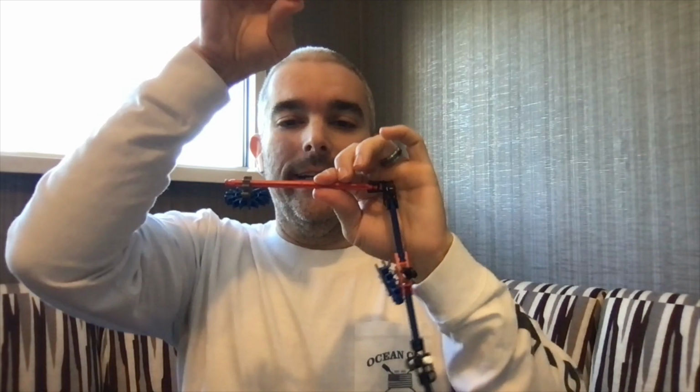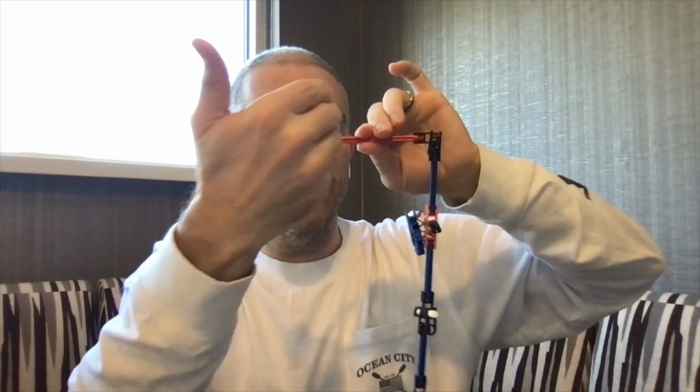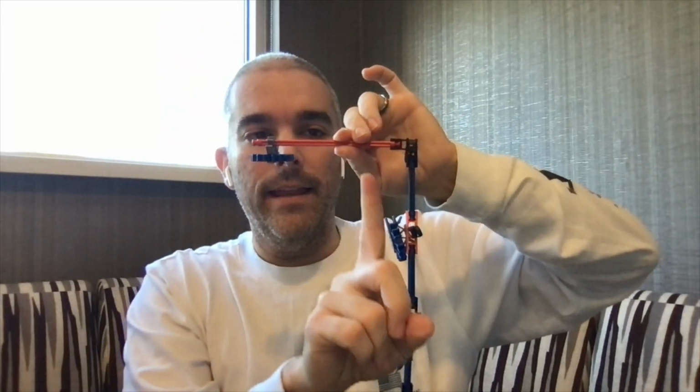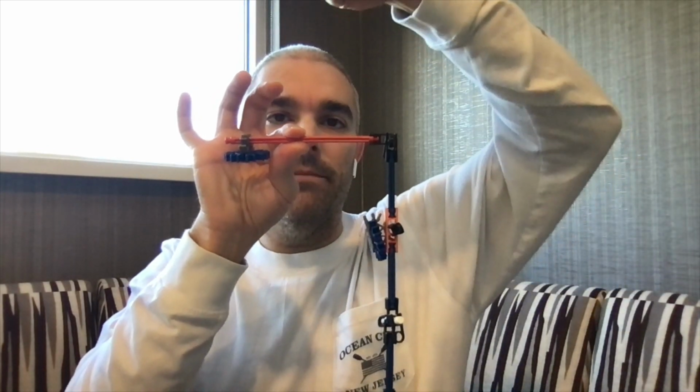All right, one more time here. We're going to look at the shear at point F. So you have to imagine, like, if I clipped this or I broke it, and so again, I'm going to apply that positive direction. Again, because this is a fixed end, I really can't move it on that side. And so it's on the right-hand side that it's going to shift. Now, again, positive shear is going to be down on this side and then up on this side. So since this can't move, this is just going to shift up. So it's going to shift straight up. And then when it shifts up, that puts us at a value of 1. So that'll put us at a value of negative 1 over here, and then 0 at the 2 supports. All right. I hope that also made sense.